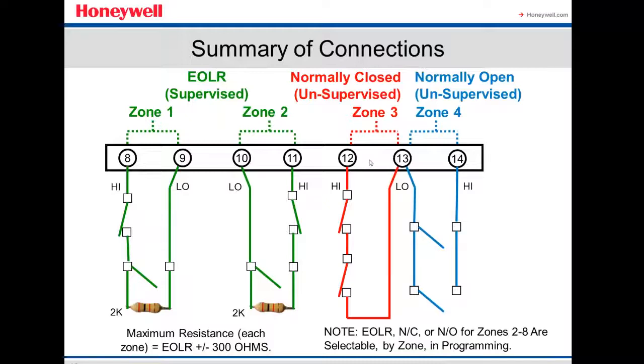So zone number 3 is going to be, for the panel, always armed, even though they can open the window. Whatever zone this number 3 is, they open a window or a door and just put a breach here, and the panel is not going to notice that the door or the window was opened. That's why we never recommend not using the resistors at the end of the line of the zone.